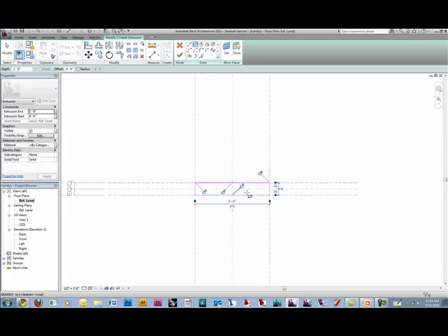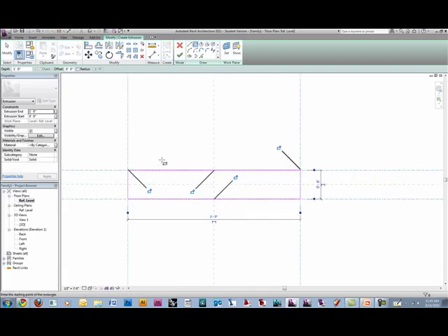and draw it right where it should be. And this is the case where you want to use the locks, because you always want these lines to move with those reference planes. If you didn't lock it, the geometry is going to stay the exact same size, and then your lines are going to flex, and you're going to wonder why the model is not parametric. So we need to lock every one of these.